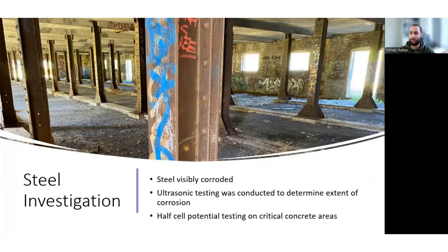It was found in areas of wetness, 70% of the steel beam flanges are actually corroded and significant thickness loss was occurring on the columns located within this old industrial area.